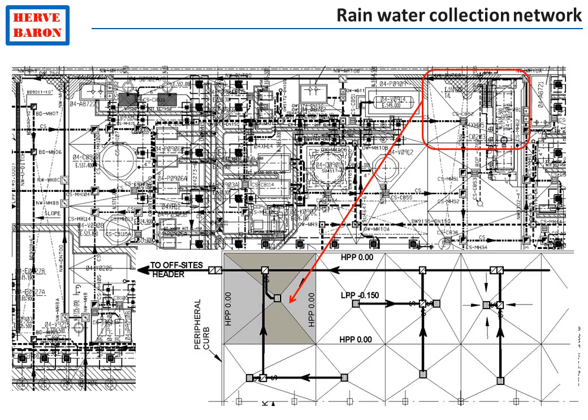The rainwater collection system, for instance, is a rather intricate collection of catch basins, pits at every change of direction to be able to clean in case of blockage. In fact, there is not only one such system, but two systems in a process plant. One for clean water, collecting the rainwater on building roofs and roads, and one for oily water, collecting water on the paving of process areas. So you see that this system of rainwater collection is rather complicated.